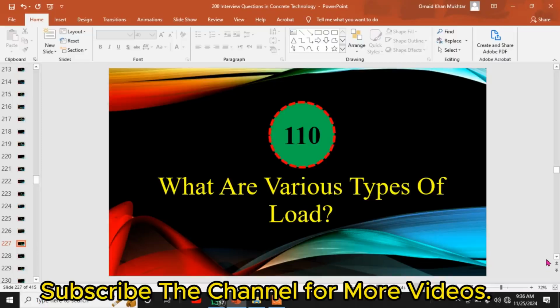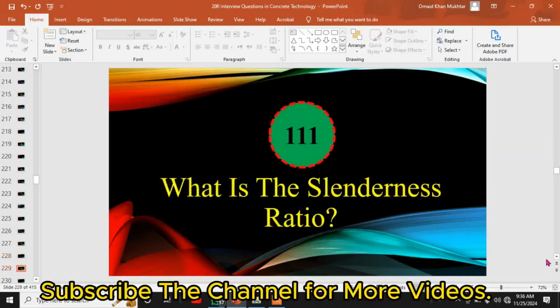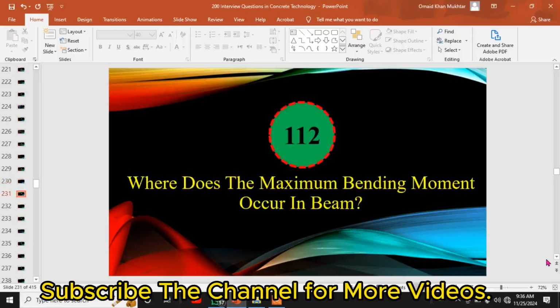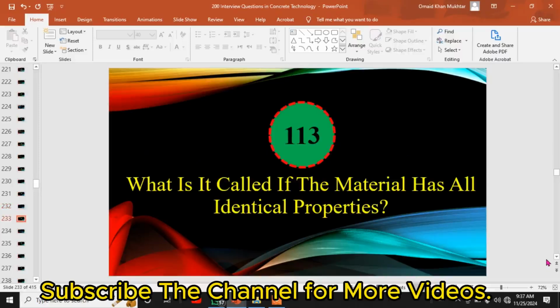110th. What are the various types of load? There are the following load types: concentrated or point load, uniformly distributed load, uniformly varying load. 111th. What is the slenderness ratio? The ratio of a structural element's column length to its least radius of gyration. 112th. Where does the maximum bending moment occur in a beam? The point at which shear force changes its sign.